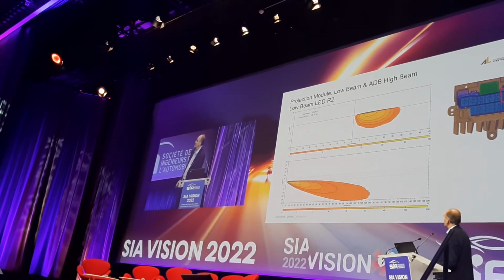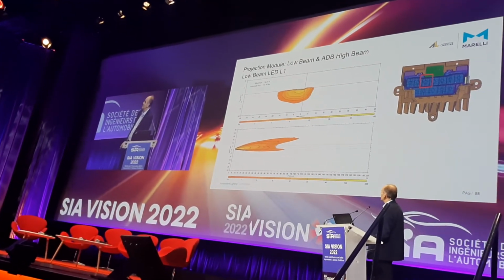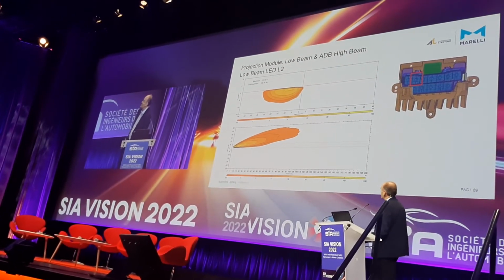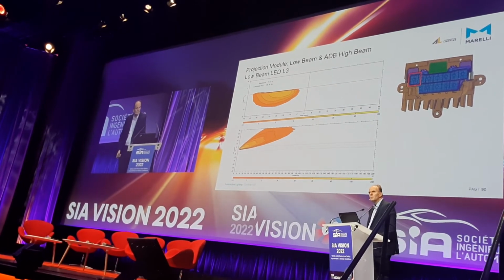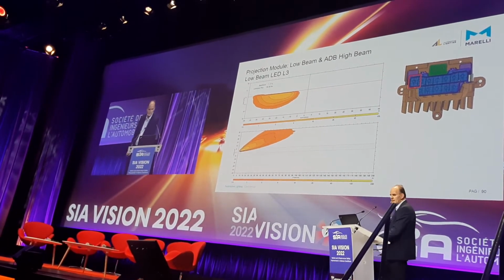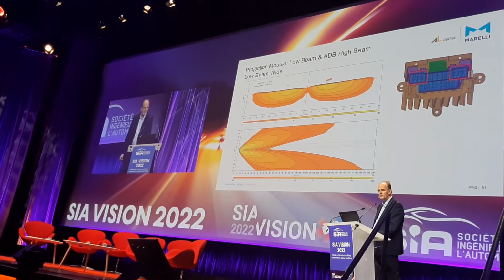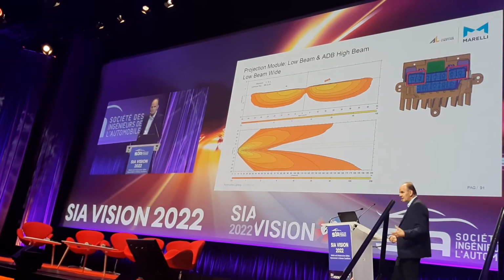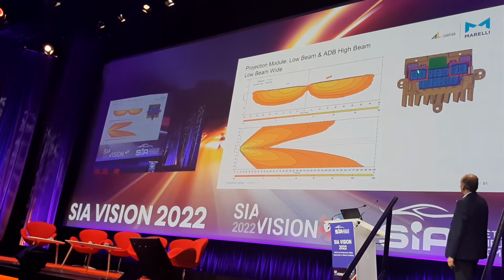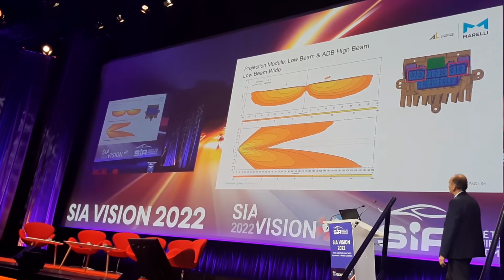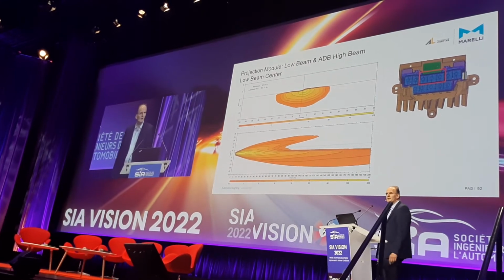The next one is for the side, the next ones are for range, then the next on the left side for the left side spread, and the next also for the outermost left side spread. So this is the option which we have technically today, and we can group these LEDs. Technically, in some modules they are also grouped, so that we have the foreground and the side spread on one electrical path and the range on the other one.